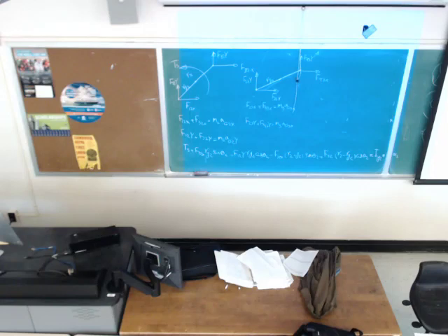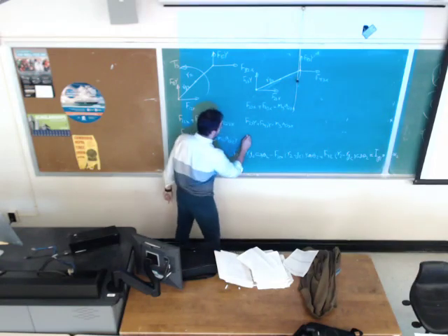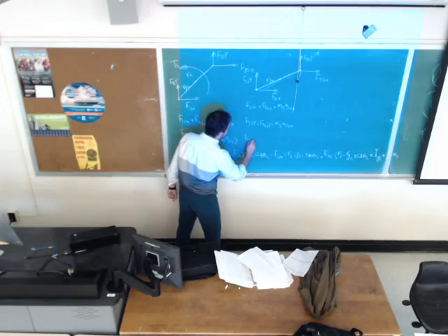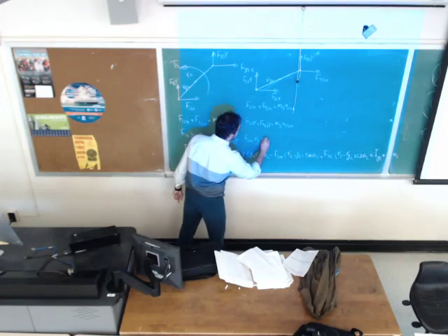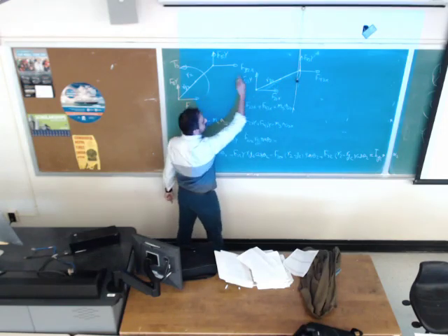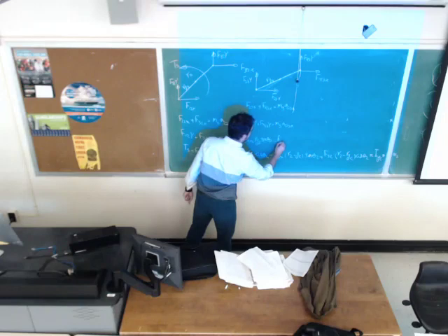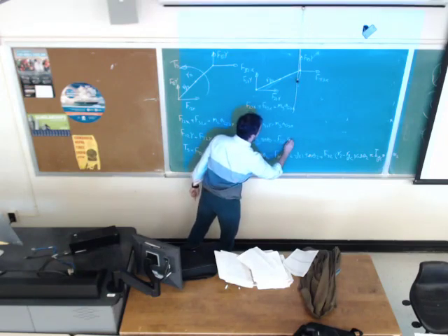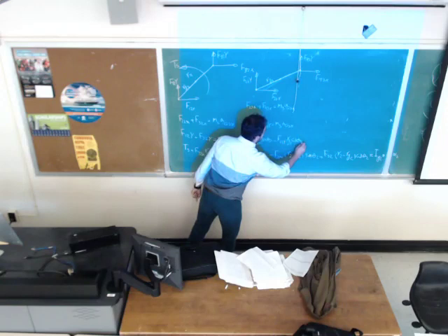This force times this vertical distance is making torque counterclockwise. This is the magnitude of the force. The vertical distance will be RG3 sine of theta 3, sorry. So it's going to be F23x RG3 sine of theta 3. This force is making clockwise, so I put negative F23y RG3 cosine of theta 3.